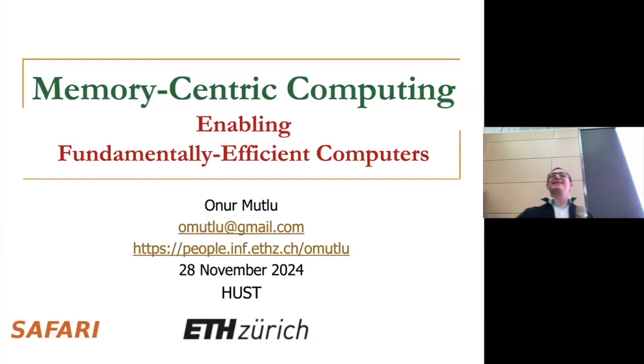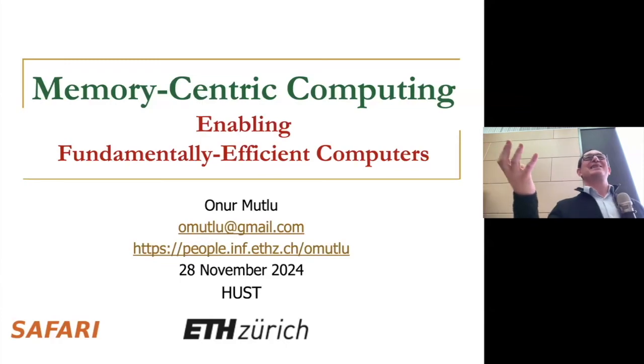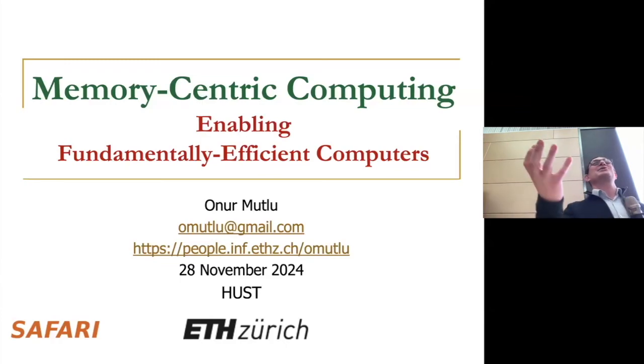So I think the answer is yes, it will affect your storage capacity. No question about that. Whenever you add some logic to a chip that performs computation, like near memory computation, you will need some space. For example, the UpMem company actually added a full MIMD processor next to each DRAM bank. And the overhead that they have is significant. But the benefits you get in some applications is also significant. So the question is, what are you willing to add, right?